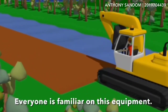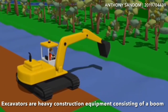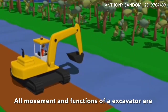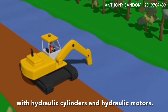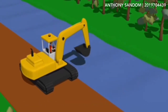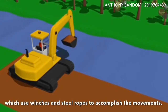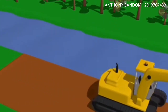Everyone is familiar with this equipment. This is the excavator, a heavy construction equipment consisting of a boom, stick, bucket, and cab on a rotating platform known as the house. All movement and function of the excavator are accomplished through the use of hydraulic fluid, with hydraulic cylinders and hydraulic motors. Due to the linear actuation of hydraulic cylinders, their mode of operation is fundamentally different from cable-operated excavators, which use winches and steel rope to accomplish the movement.